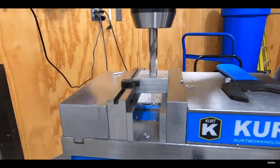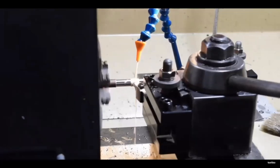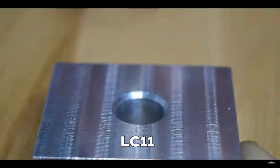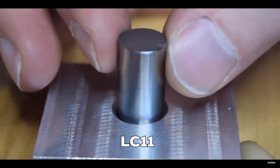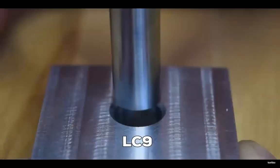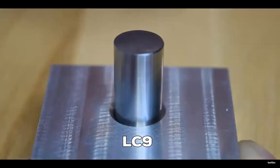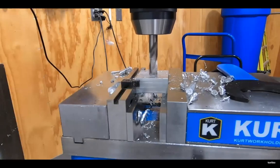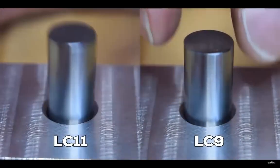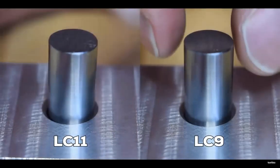These tolerances are extremely loose, so drilling the hole with a regular drill is sufficient. Hitting the shaft tolerance on the lathe is also no problem, and other processes like forming and extrusion will probably hit it as well. This fit is used where you don't need accurate alignment of the mating features. The clearance around a bolt is a good example of this, since you typically don't use a bolt for precision alignment. This is a slightly tighter locational fit, LC9. It provides less clearance and has a tighter tolerance than LC11. This is probably about the tightest hole tolerance that can be drilled, but turning shouldn't be a problem for the shaft tolerance. You can see that the LC9 fit is a bit tighter than the LC11, but both can still be easily achieved with standard equipment and tooling.